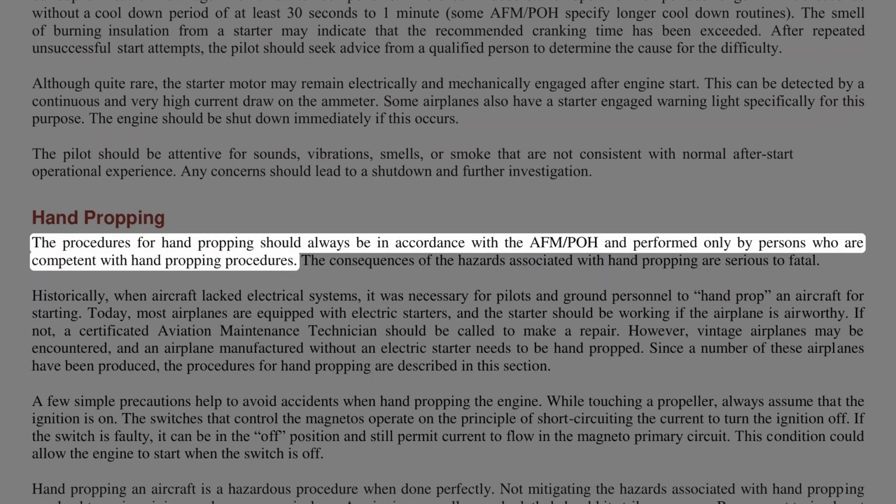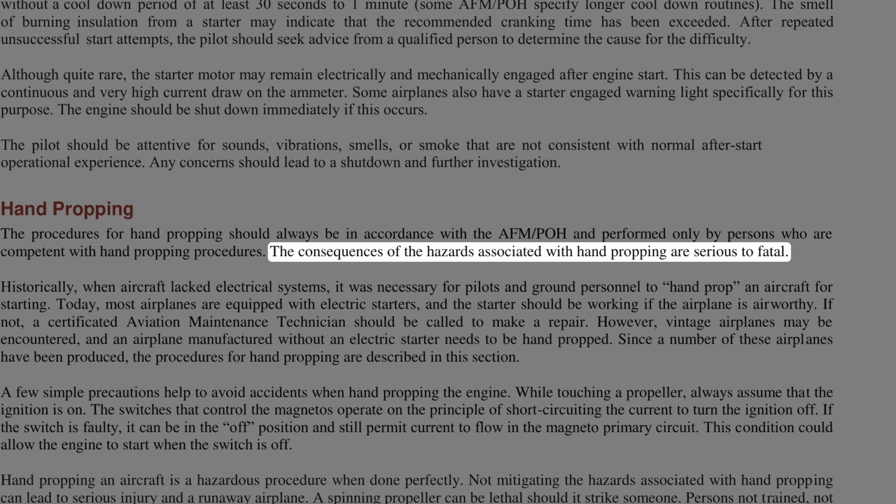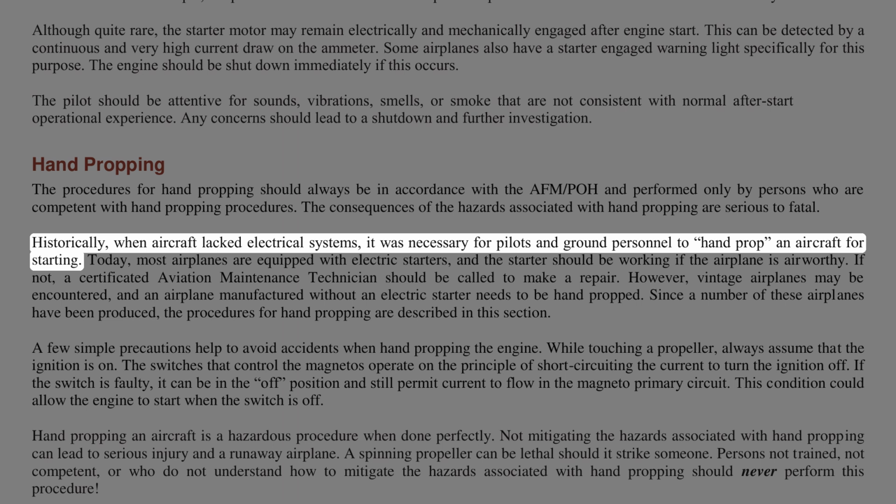Hand propping. The procedures for hand propping should always be in accordance with the AFM/POH, and performed only by persons who are competent with hand propping procedures. The consequences of the hazards associated with hand propping are serious to fatal. Historically, when aircraft lacked electrical systems, it was necessary for pilots and ground personnel to hand prop an aircraft for starting. Today,